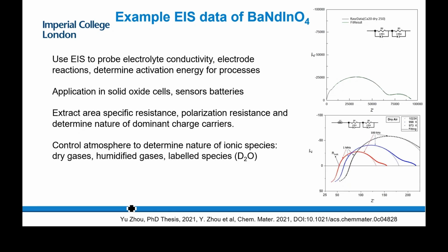This is the imaginary. So we have an impedance in ohms, so we can measure that. And when we start to think about fuel cell kinetics and thermodynamics and the operation, we'll use current density, and therefore we'll be looking at area-specific resistance, in ohms centimeter squared.